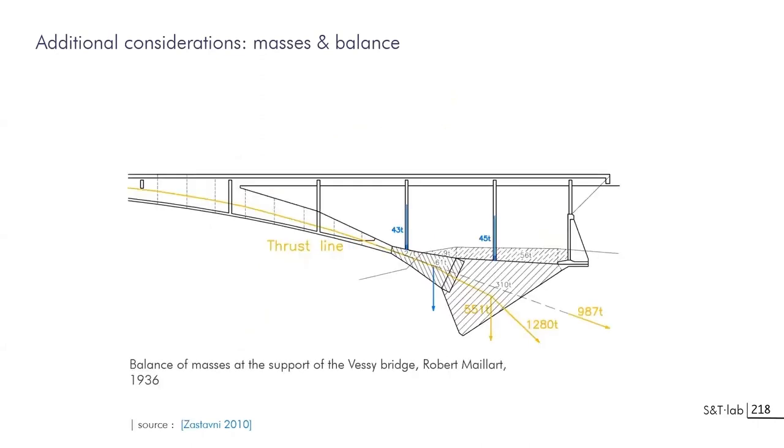There's another example coming from practice from Robert Maillart. This is the foundation blocks of the Salginatobel Bridge. You see that the problem in such an arch is that you have two quite horizontal reaction forces. And if you are just pushing in this direction, you have something that is too horizontal to be supported by the ground. So the strategy is that you have to change the direction of these forces.